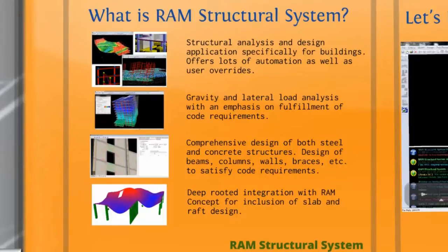And it emphasizes both the design of the elements and analysis. Okay, so not just analysis, actual design of the reinforcing in the concrete structure, automatic sizing of structural steel elements if you have those, foundations as well. And it has very good integration with RAM Concept. RAM Concept can actually be run as a module within RAM Structural System, and you get good reuse of information as well, and we'll be seeing that here in this portion.